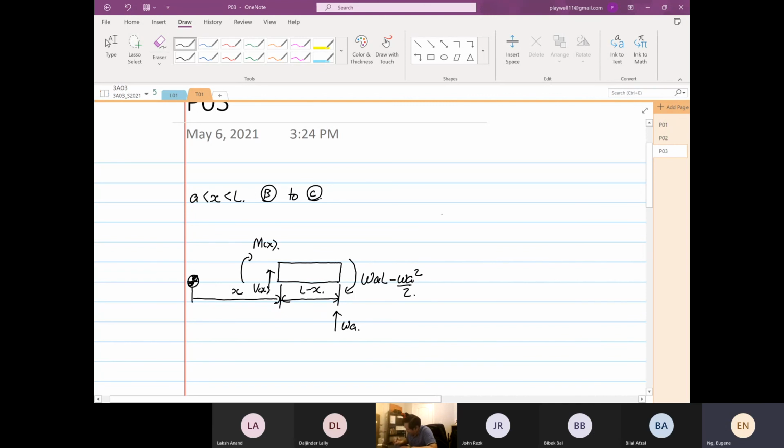Okay. So static analysis. So I mentioned about forces in the Y direction is equal to 0. Right. So you have omega A, plus V as a function of X is equal to 0. So V as a function of X is equal to minus omega A. Exactly the same, right? Now we're going to take moment over here, right? We're going to take the moment at that point over here.